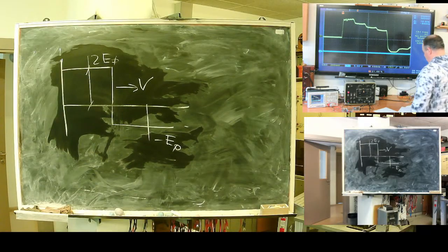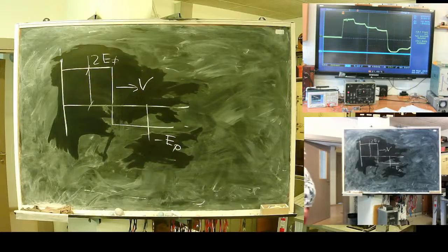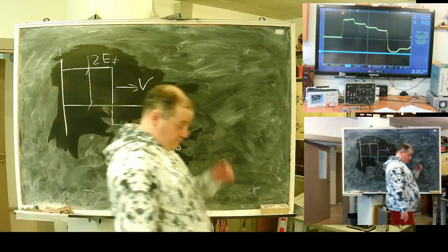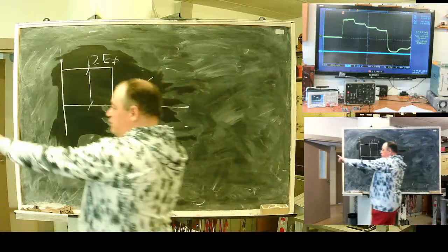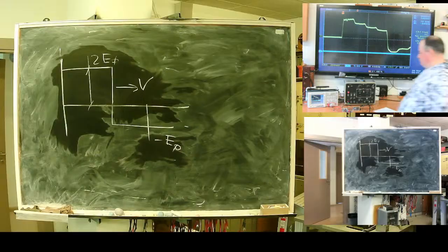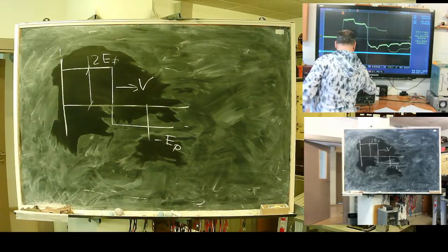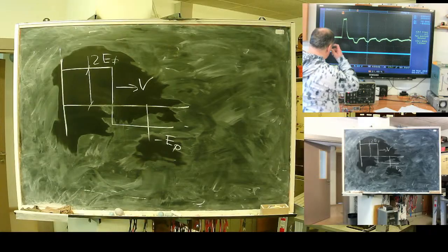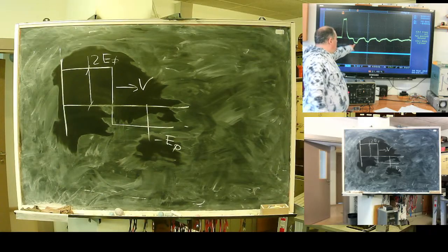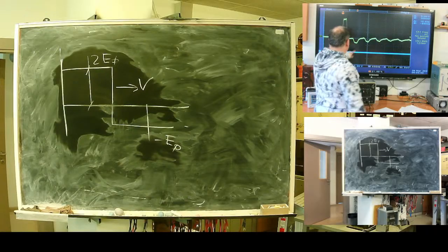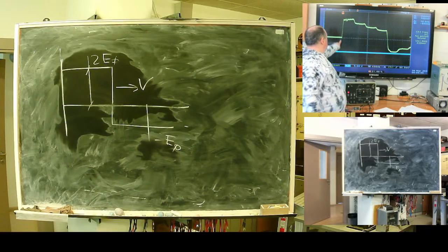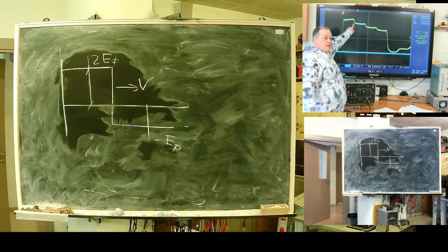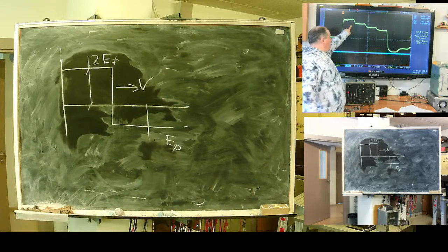In general, if the resistance at the end is greater than the line wave resistance, we see positive reflection. If less, negative. Here, short circuit. For the short pulse, here arrives minus E0, here arrives plus. This is the double propagation time of the line.